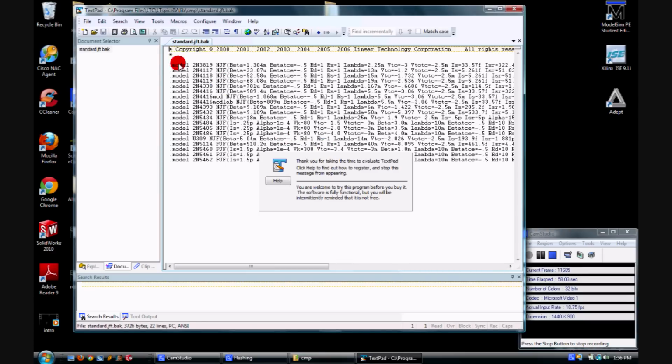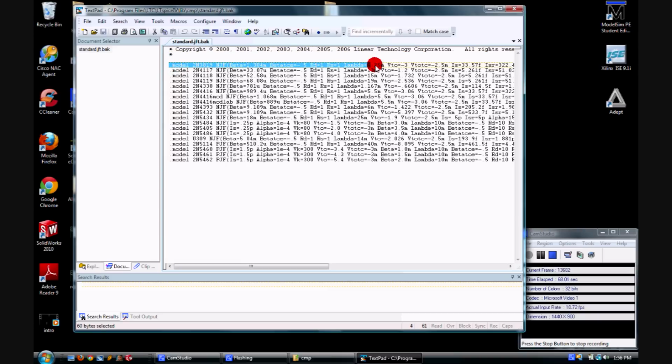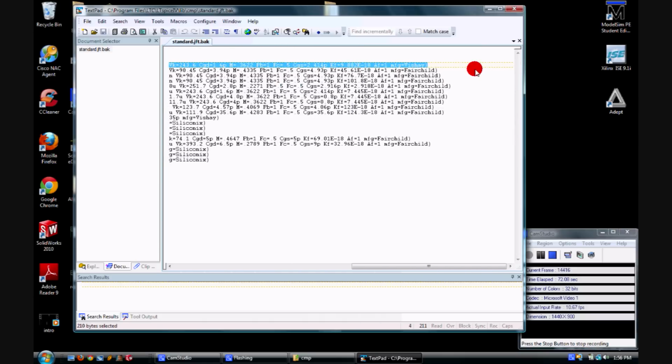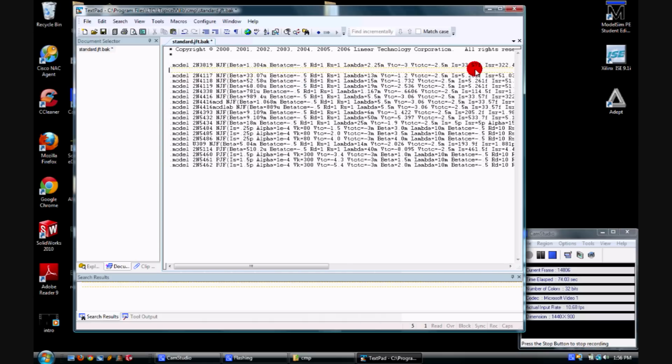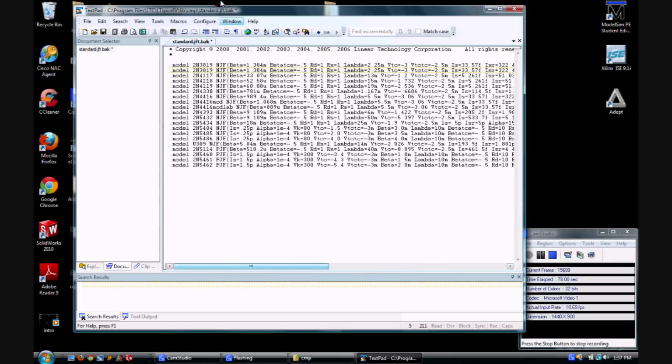And this brings me to a bunch of models that you can find in SPICE. And if I want to make a new one, what I do is I just copy the .model line, paste it in a new line, and call it something else.